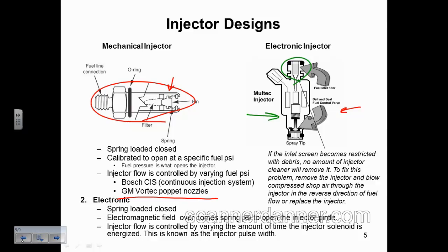And sorry, Lucas. But if you get debris on that screen, you can't clean it with any injector cleaner, because that is such a fine screen that injector cleaner is not going to dissolve rust particles and things like that, and that's what you get in there.